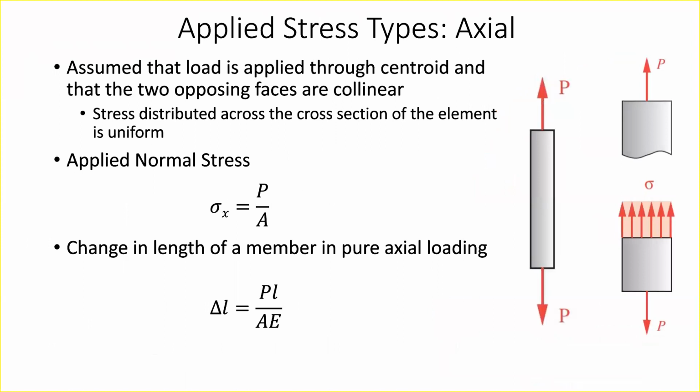Okay, so we'll go back to the definitions of stress and strain I described earlier. I mentioned that there are certain patterns of loading that you need to expect. Whenever I'm designing a new part, I always look for these patterns initially. This very basic case is what you would refer to as axial loading. You just have some part and you're applying two loads to it on opposite sides. This is really the most basic you can get with any type of loading. But you'd be surprised how far you can go just knowing these basic patterns and applying them to your parts.